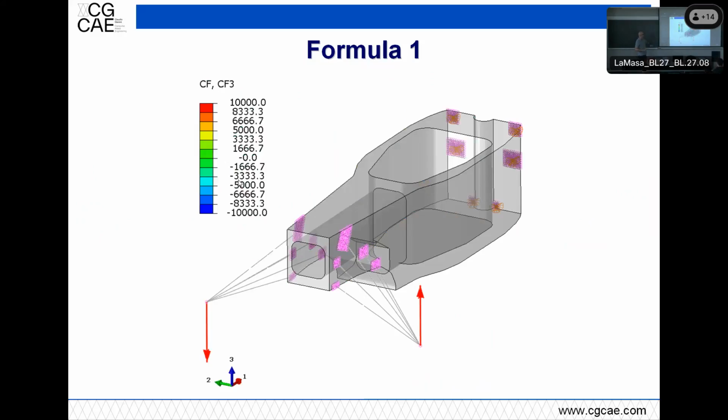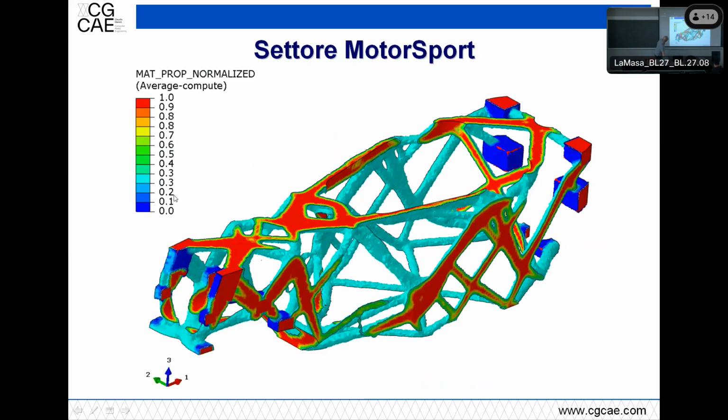There are many requirements, as we have seen. We have the load on the roll hoop here, which is then transmitted to the monocoque, so you also need to check that one. You have the side crash, you have the front crash. There are many requirements that a survival cell like that needs to withstand. Torsional stiffness is more for the performance of the car rather than for safety. And this is what you get.